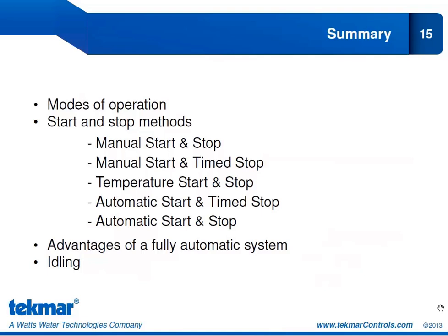The other type of application where it would be recommended would be if you're retrofitting an existing system. So you're going to add Snowmelt Control 654 with the automatic start and time stop sensor, so that you can move away from the manual operation and gain at least some degree of automatic operation.